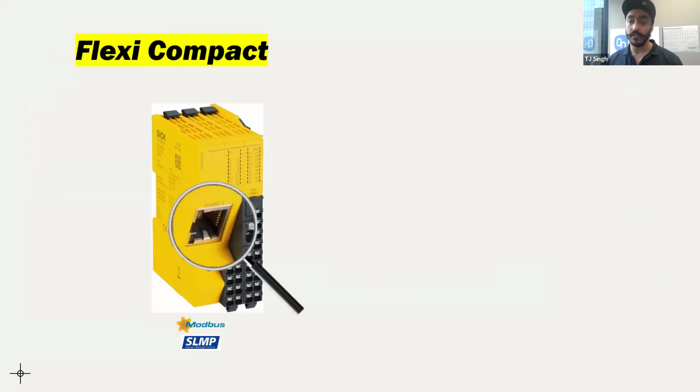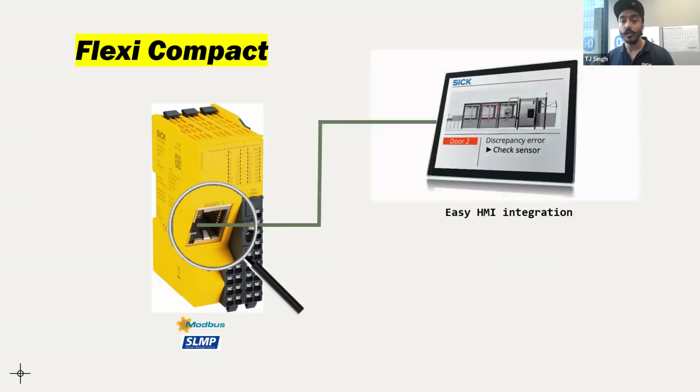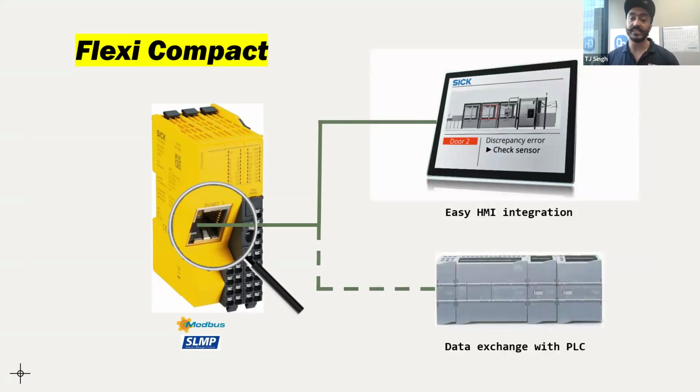Something that's another unique to this safety controller is that it has a model which comes with a built-in port for Modbus TCP, so you can integrate it to an HMI or to a PLC directly to get any kind of diagnostics from your safety system.